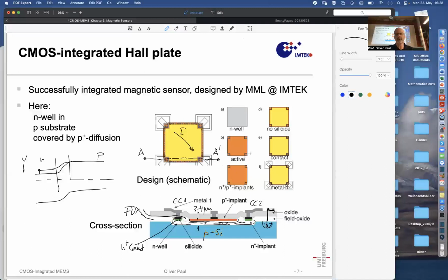And then a grayish layer is deposited. It is opened to open these contact vias. That's this here. And then a metallization is deposited to contact whatever is below. And then we're done to this point. And then comes another intermetal dielectric, the second metallization, and the passivation if it's just a two-metal process. You have seen that in chapter 2.